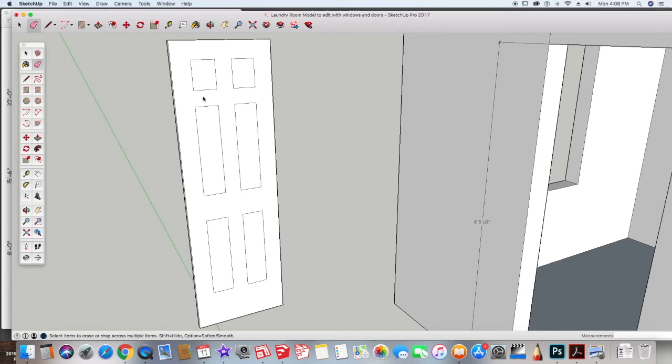And here I'm going to push this in, not very far, because if you really look at those panels, and I'm simplifying the panels a little bit, it really is not pushed in very far. And again, it's not very thick. So I'm going to push that panel in 1/4 of an inch. I'm going to double click on all of those so that it applies to all of them.